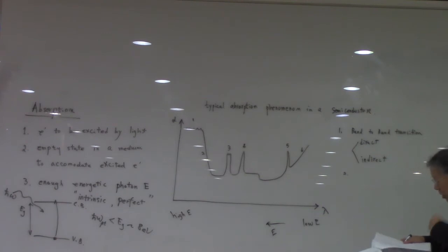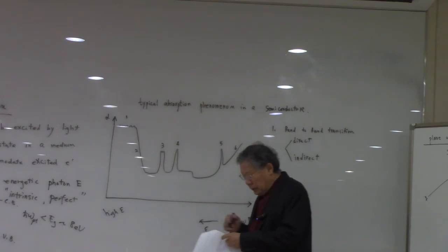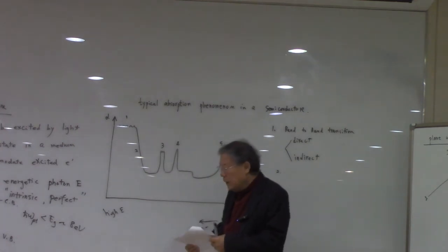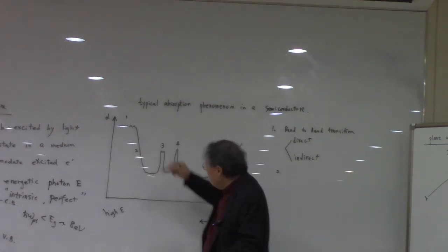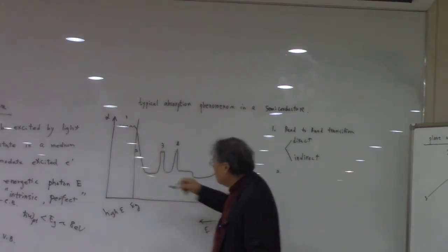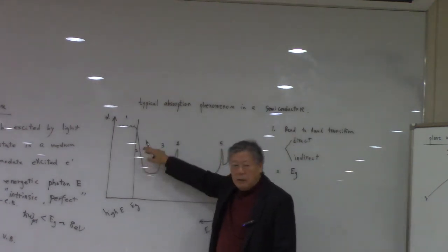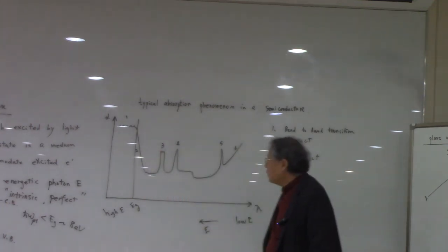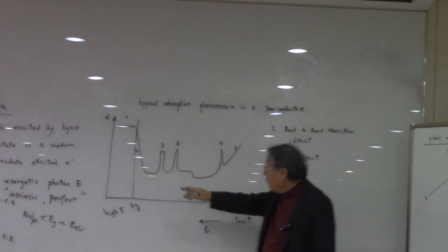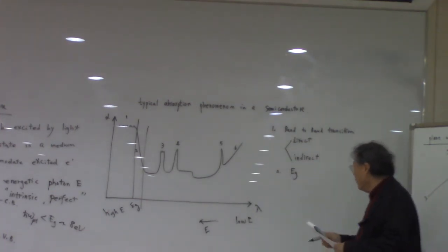So if you have a small photon energy, then statistically it's going to decrease in this fashion, and then we can see that the band gap energy is going to be related on this number 2, somewhere in between these two, right? We cannot directly say that you can measure the band gap correctly with the absorption constant, but the band gap has to lie in between, in the region 2, right?